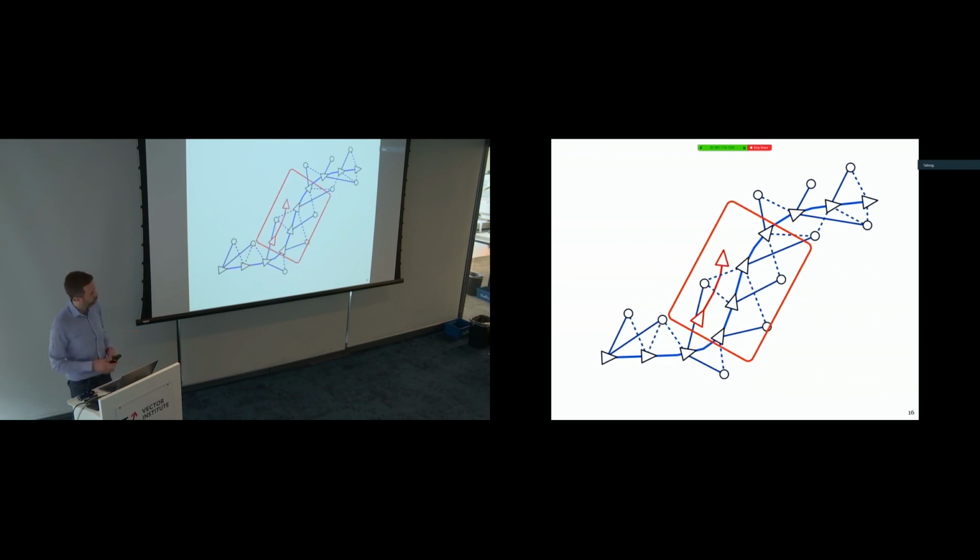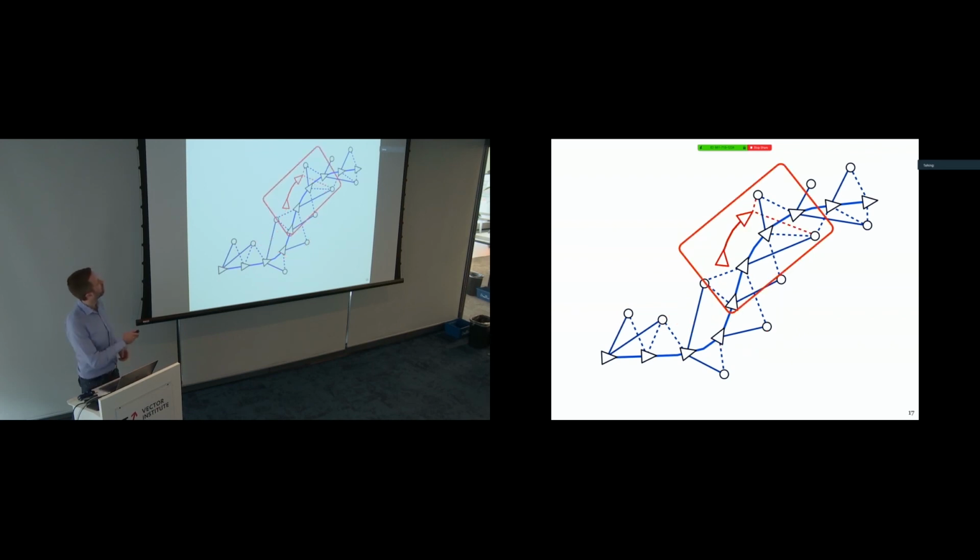And then if we move, we may or may not actually get some more matched landmarks, but we can always estimate this using visual odometry. And then we can move a little bit more. And maybe now we reacquire some features, and we can determine the transform directly between the live pose and the one in the map. And so this just progresses.